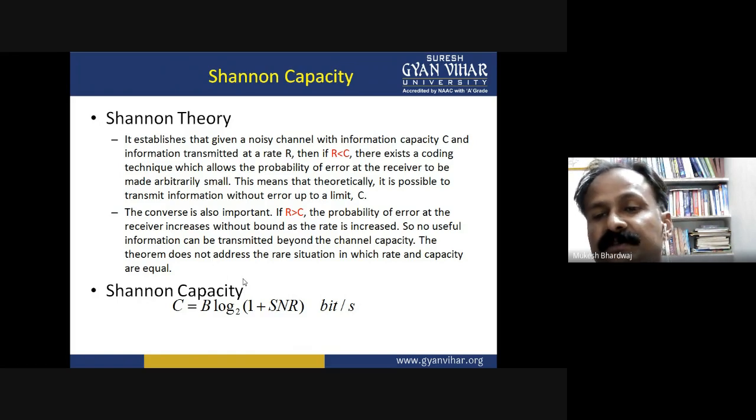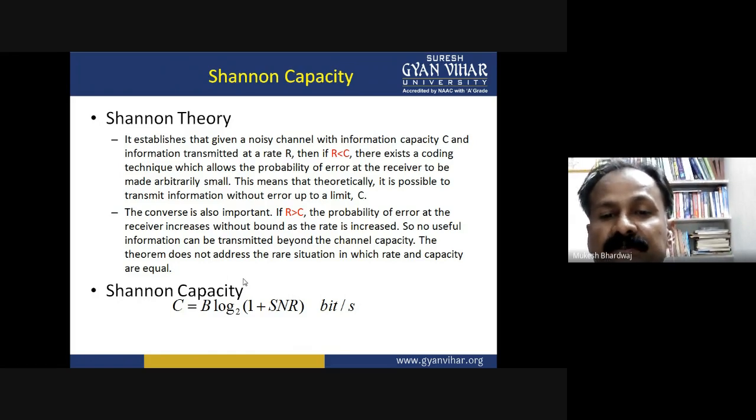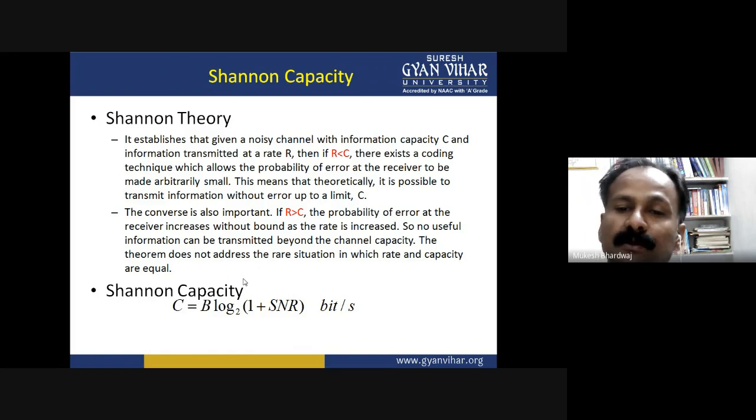Transmitter: the function of a transmitter is to process the electrical signal in different aspects. For example, in radio broadcasting, the electrical signal obtained from the sound signal is processed to restrict its range of audio frequency, up to 5 kilohertz in amplitude modulation radio broadcast, and is often amplified. In wire telephony, no real processing is needed. However, in long distance radio communication broadcast, signal amplification is necessary before modulation.